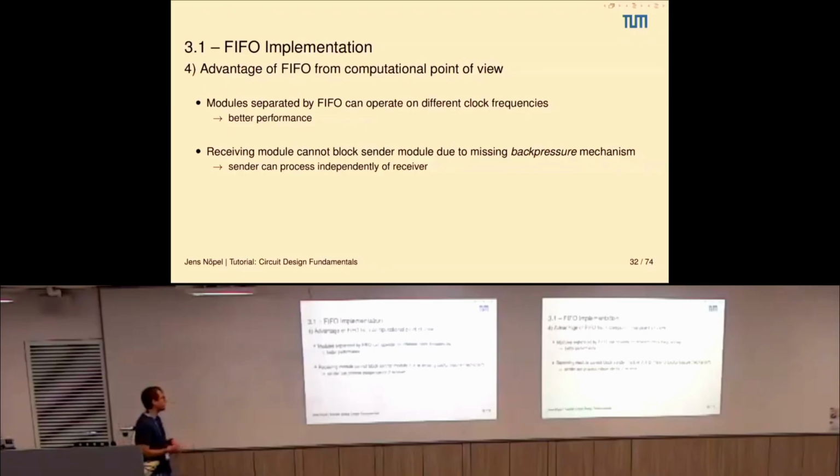Okay, so if the FIFO is full, then either you also have this handshaking protocol that allows the back pressuring. Then it will tell module A, I'm not able to receive any more data. Please don't write to me. Or you just drop packets. All right, anything else? No, okay. Then that was it regarding FIFO implementations.